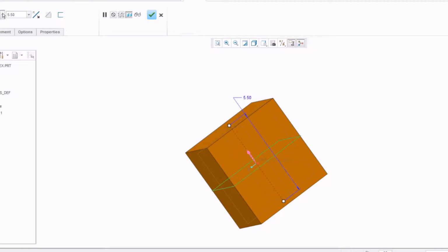Very useful. The last one, not very applicable here, but you will see a demonstration of it, is actually to extrude to a certain surface. So with this, if you had a feature already modeled, and let's say you had another feature off, maybe up to the left, you can actually extrude it and tell it to stop at the surface of the first feature. Don't worry, we're actually going to demonstrate this one.